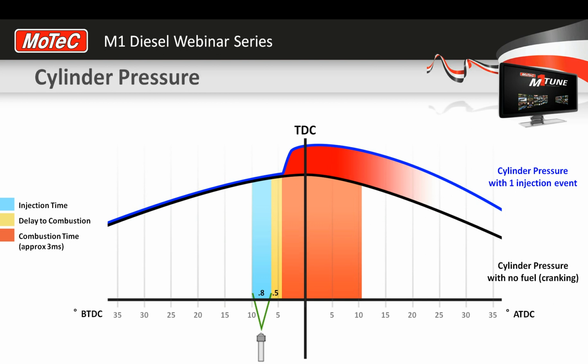So each droplet becomes its own little combustion area, I suppose. So it makes a very fast chain reaction. If anything doesn't instantly self-combust at that first moment when all the droplets get hot enough, then it certainly combusts very quickly as a result of all the existing burning droplets of fuel. So long story short, you get a very large and very quick pressure rise because of all of this fuel almost burning all at once.